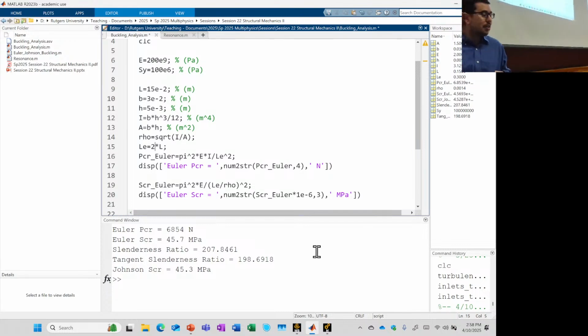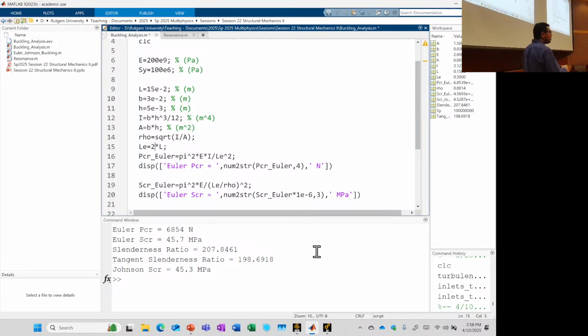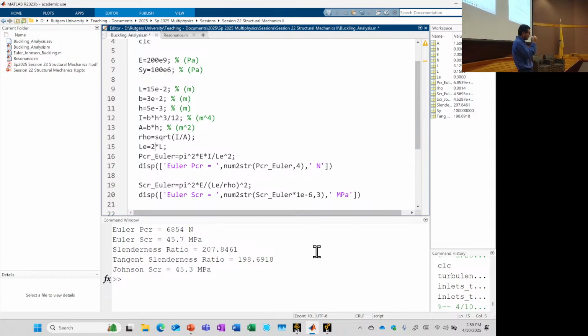Experiment always wins, right? As you get more and more advanced and you get experience, let's say you're working for company XYZ, and you've been making these things, and you've got the simulations, you've got a general idea. Even though this is a slightly high number, I've done this analysis in ANSYS or in your finite element to get my numbers to agree, then you're able to say, okay, I can trust my analysis, I don't have to do an experiment.